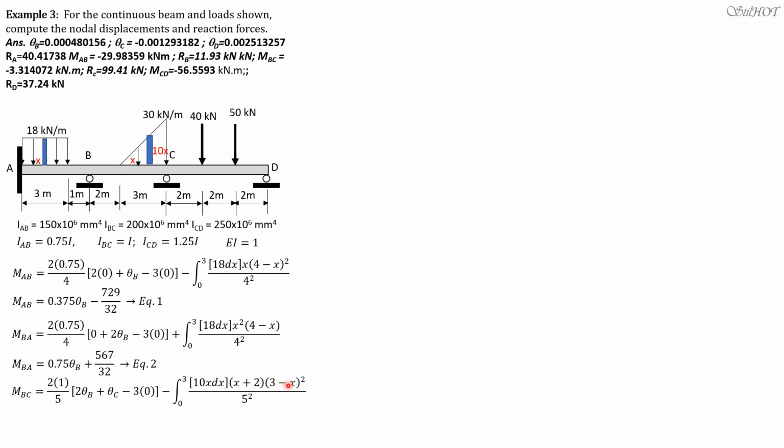So simplifying, moment BC is 0.8 theta B plus 0.4 theta C minus the value of the integral, which is 8.64.